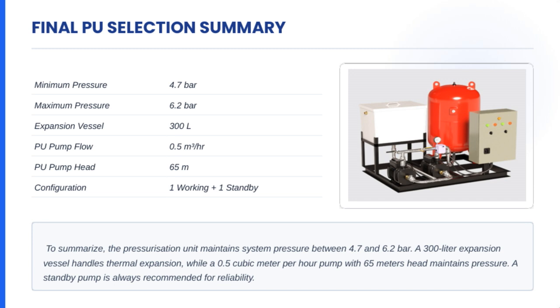We've also included a configuration with one pump working and another on standby. This setup boosts system reliability. If the primary pump needs maintenance or fails, the standby pump can seamlessly take over, minimizing downtime. Overall, these specifications are carefully selected to ensure the system remains stable, efficient, and reliable, supporting the overall theme of designing robust pressurization solutions.